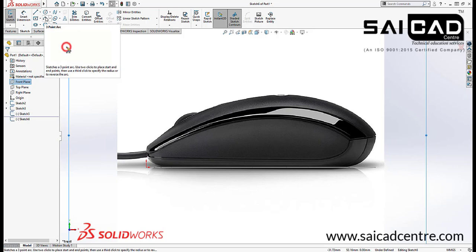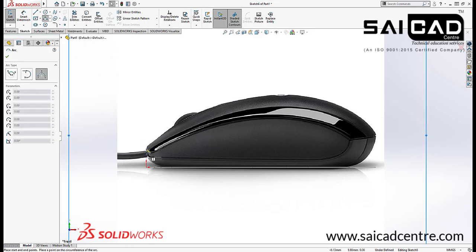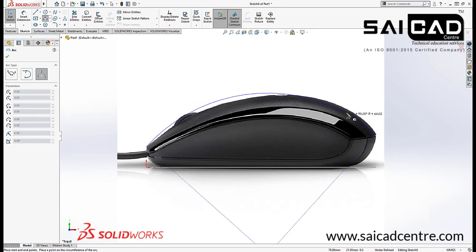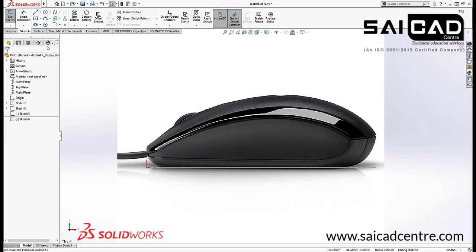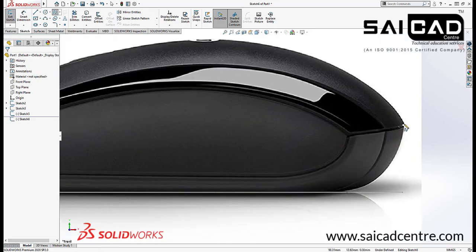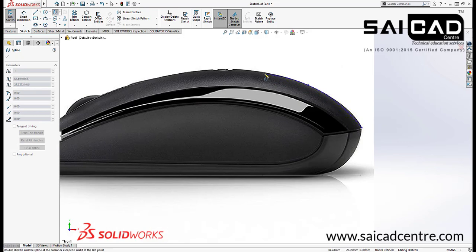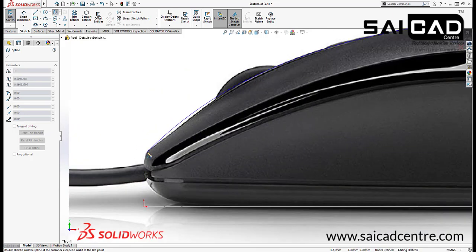here, or I can now just use the spline from here, because if I create an arc like here to here, my curve will not match here. You can see the curve is not matching. So to achieve that, we have the splines. First one is the point to point, or the fit. I can use the shape directly like that. You can see the spline will match directly, and we can just create it like that.